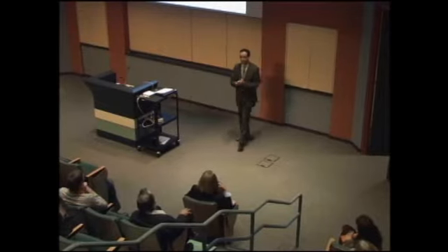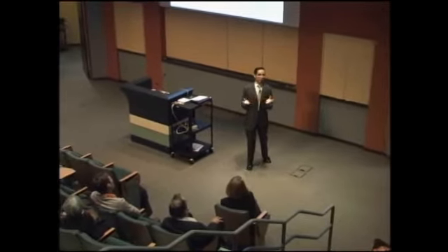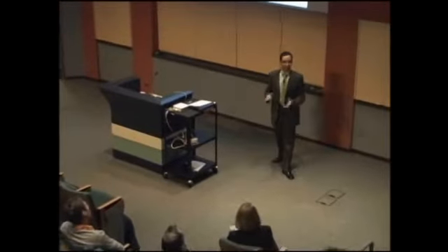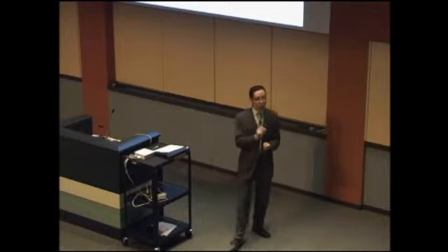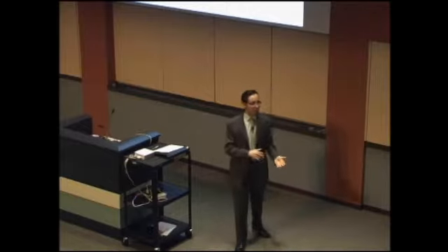Right, so for the first part, Monte Carlo simulation really has that advantage, it allows us to quantify uncertainty. For the closed form solutions, it was not possible until these recent endeavors where we get the full uncertainty. That was the drawback of the existing analytical solutions. So I think we are heading towards that path. Now, these expressions that we have for the analytical solution only apply to radial systems, and those are probably the most basic radial systems. But nonetheless, they are the starting point, and actually we can do those calculations very efficiently, and we hope to start adding loops. That's the next step in complexity.